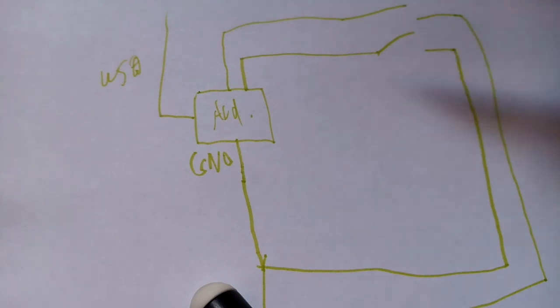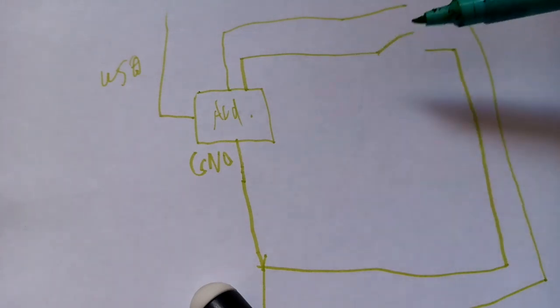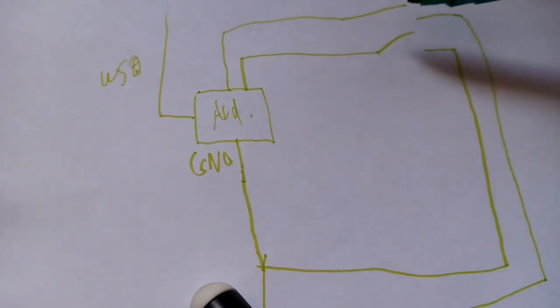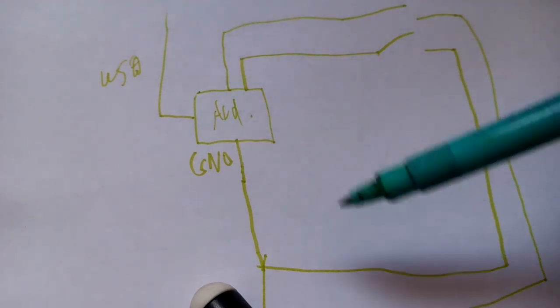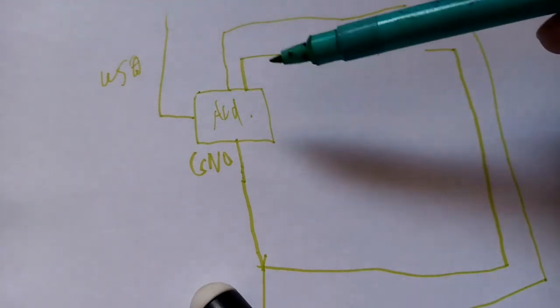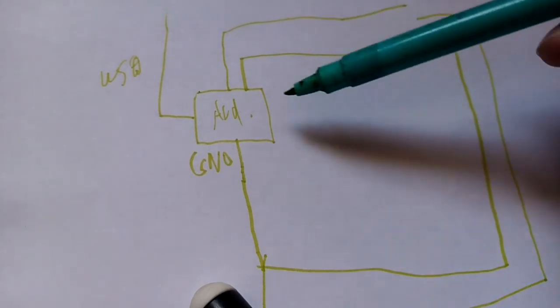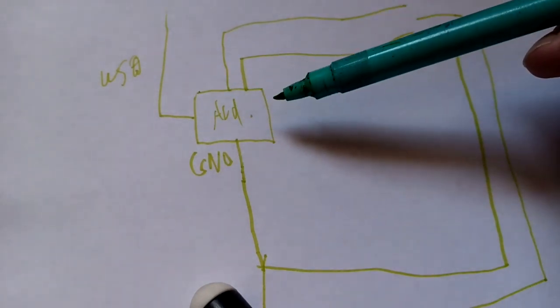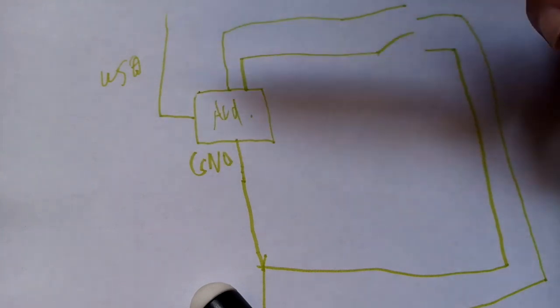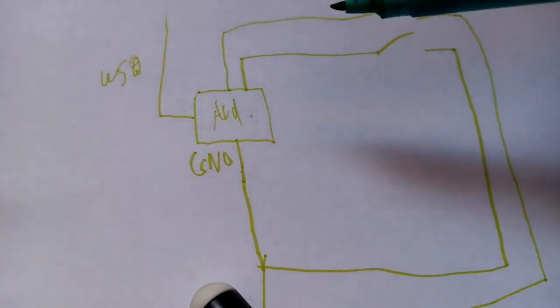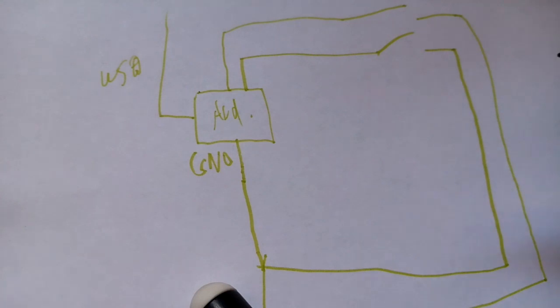Essentially, with these two switches, we're going to write code onto the Arduino so that when this switch is closed, it creates an electrical circuit, it goes around to the ground, and the Arduino recognizes this. It'll read this pin, and if electricity is flowing through it, we'll program this chip to send a keystroke through the USB cable and off to your computer. This is essentially how the whole panels work. They work on the premise that they are just fancy keyboards.